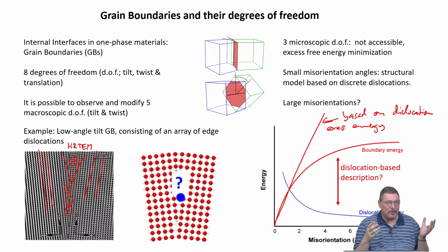But in principle, you have to assume that twin boundaries are boundaries which do affect a lot how dislocations transmit through a grain and also through that boundary or not, because they are really obstacles. But in terms of stored excess energy in your material, you can count the twin boundaries out because they contribute only very little.